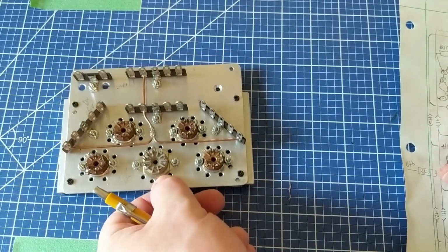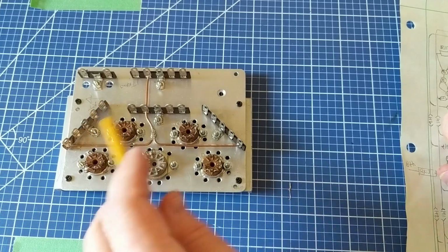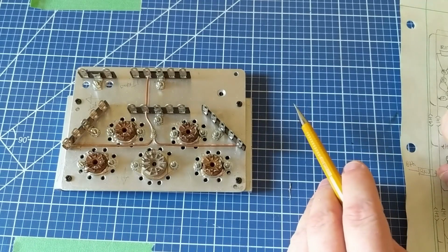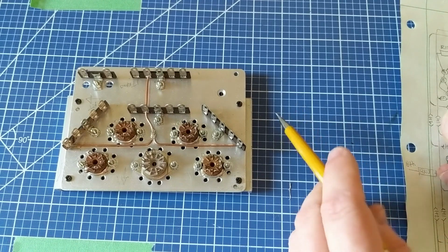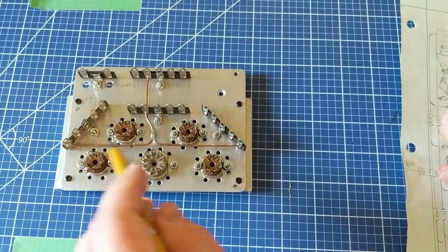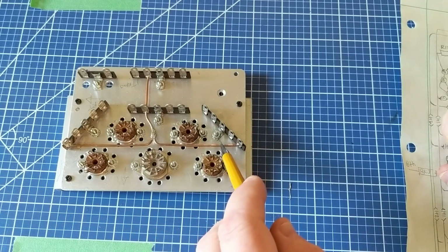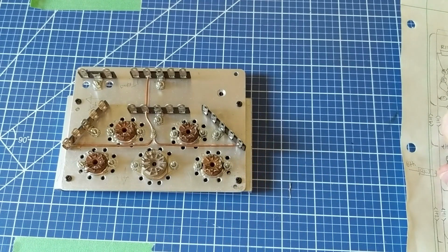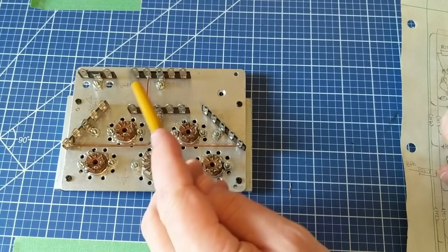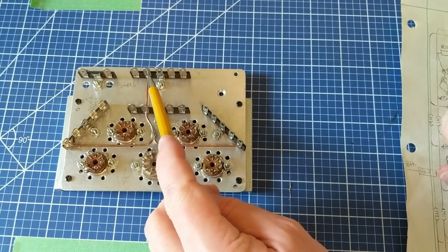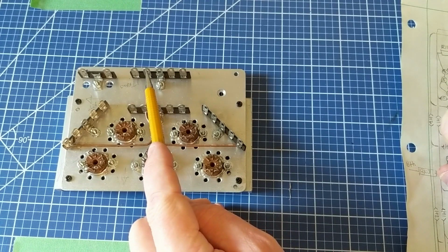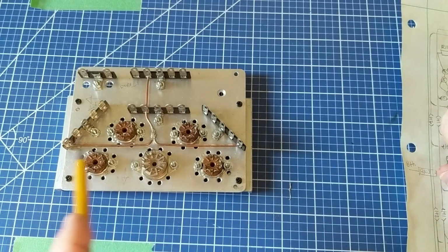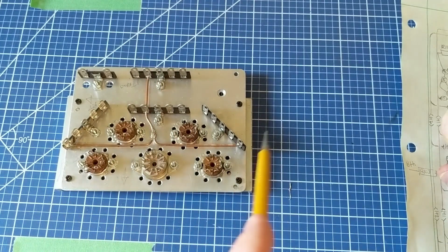This is a bottom view of it. I've already started putting in terminal strips for the different tie points for the passives. I use a common ground bus bar in the circuit to give me a good solid ground, and I like to use star ground points in my amplifiers, so this will go back to the star point, or the source point for the ground for the entire amplifier, and this becomes just one branch of the grounding star.